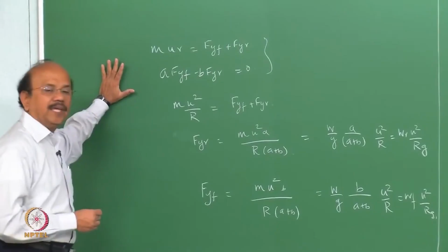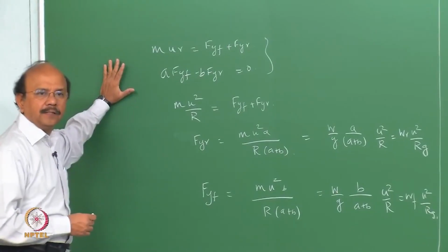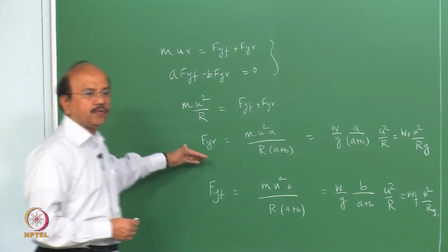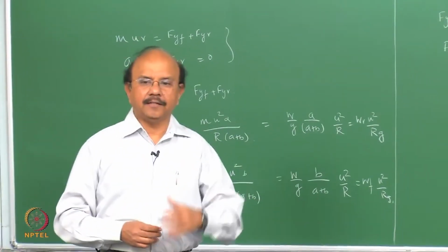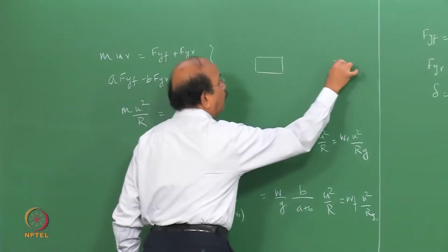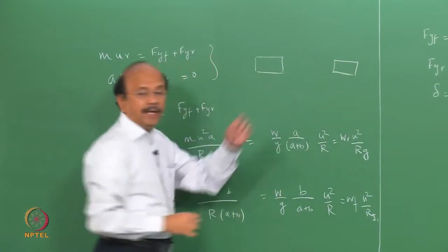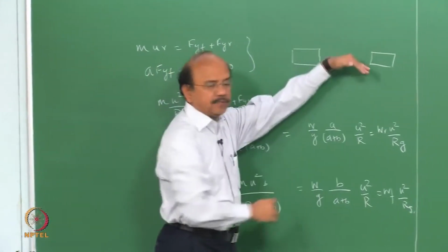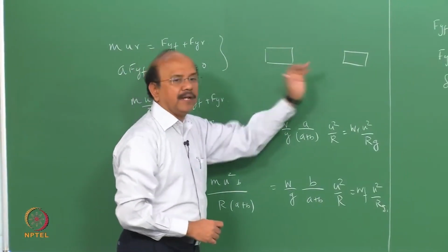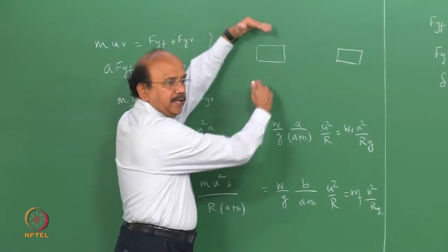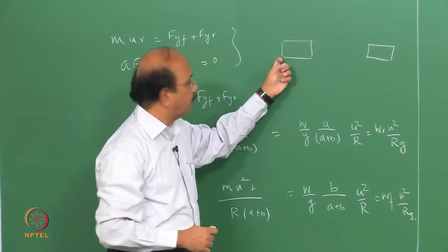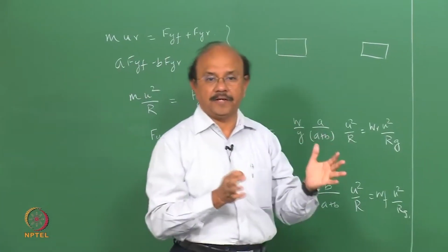One of the key things that we found when we started writing down this equation is that the two forces, that is the force acting at the front and the other acting at the rear. Remember that we were looking at the bicycle model, where the left and right tires are collapsed into one tire. There was some confusion. I said front and rear in the sense that front and rear each have one tire where the left and the right tires are collapsed into one. So the stiffness of this tire is the sum of the stiffness of the left tire and the right tire.